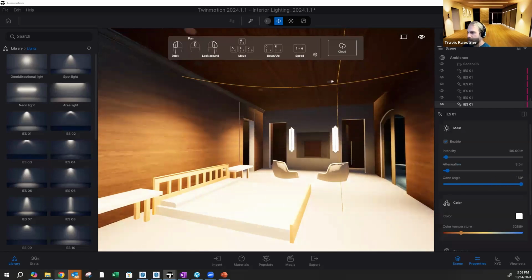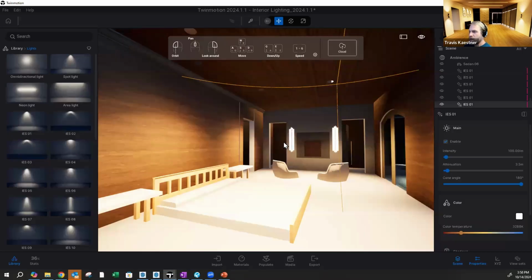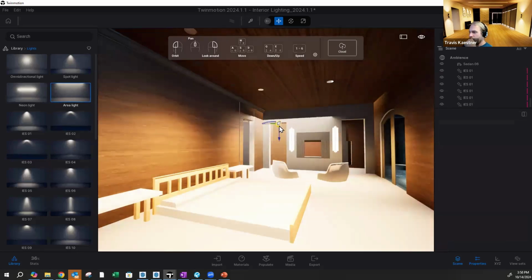So when you're specifying, we'll go over it, but look at the spec sheets, look for something with higher lumens, and look at what you're picking out. Even that, with the light recessed a little bit up into the trim, will help eliminate glare and give a little more focus and control. Because when you're mounting it in a low ceiling, that's when you experience glare, when the light is in your peripheral vision.